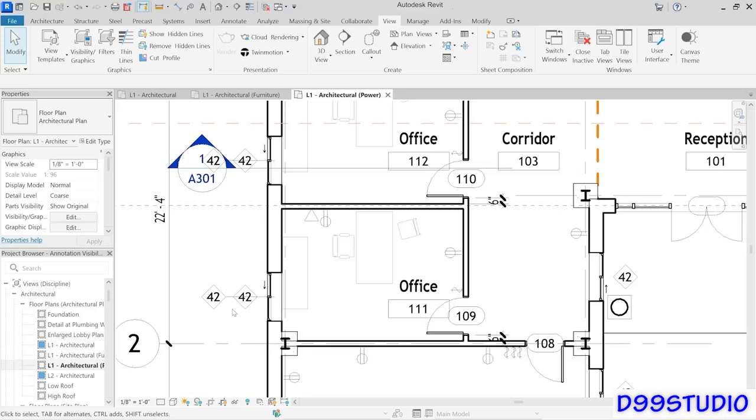Now, I understand why folks' instinct is to hide the geometry. You know, they're worried, oh, just in case I'm going to hide it, we may want it again later. But that's not the way that annotation is designed to behave in Revit. In Revit, model geometry is visible in all views, so therefore we want to hide or show when it comes to model geometry. Annotation, by definition, is view by view, therefore we want to either add the annotation or remove it.